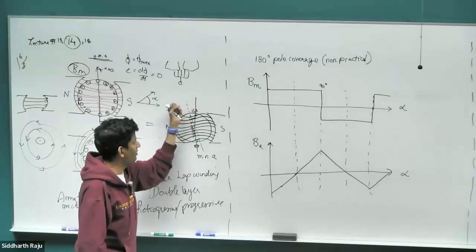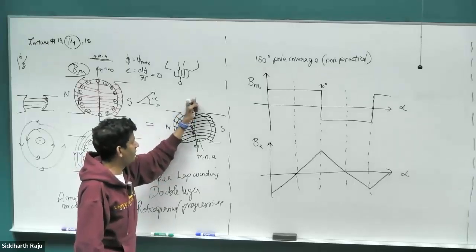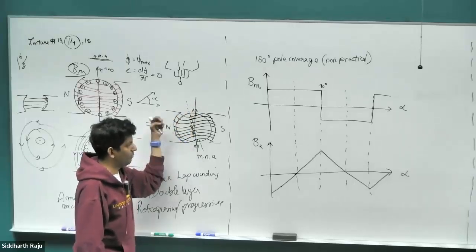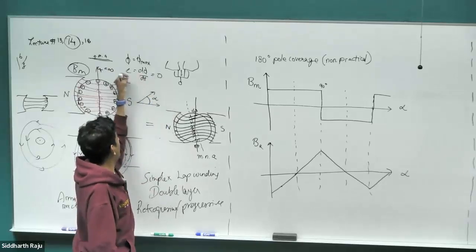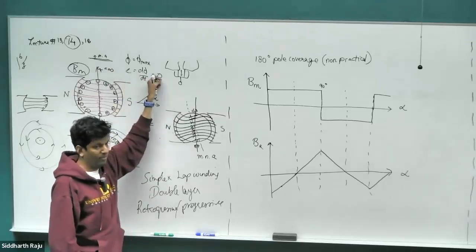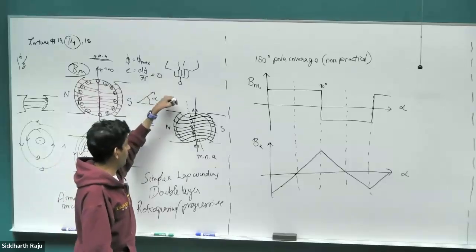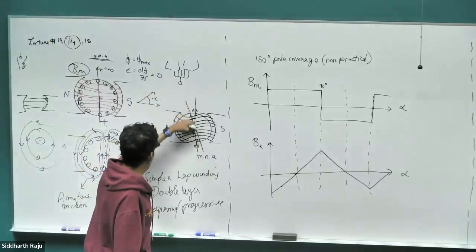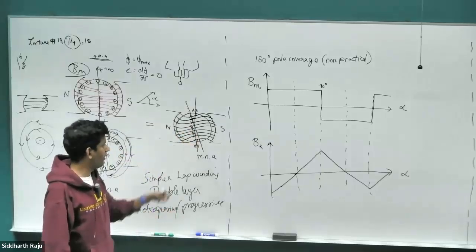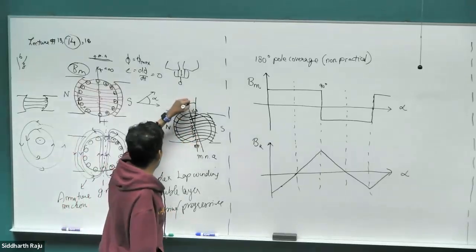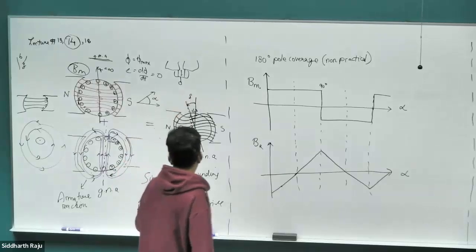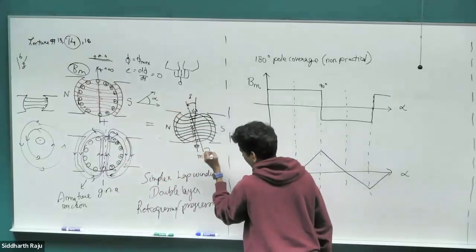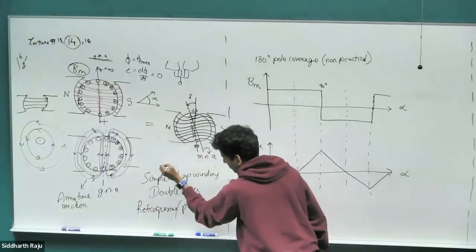So as this angle changes from some angle just before 90 to 90 degree, there are still some field lines which are changing, which is then going to lead to an EMF that's non-zero. Right? So where is that EMF going to be actually zero in this case? It is again going to be the case where the loop is perpendicular to the magnetic field lines. It's going to be slightly shifted out by some angle delta. And this newly shifted location is called the magnetic neutral axis.